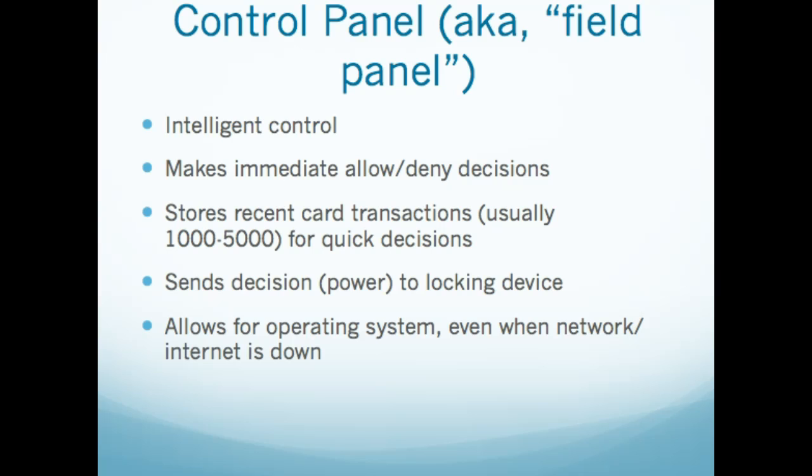And so when you start to put electronic access control in, if you put too many card readers in a building, for every 2 card readers at $5,000 a piece, let's just say by the time you get them wired and put together, the control panel itself is going to run you at least $10,000. You're adding now onto the cost. So not only is it the cost of that reader and modifying the door and everything, but for every 2 doors, you have to have one of these control panels to make the decision. You have to pay for those too.